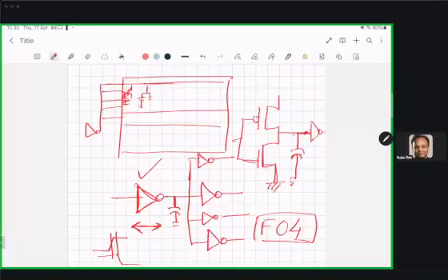On the other hand, we said that we need large enough memory, otherwise how will we do these big matrix manipulations? For example, I want to do image processing. So I have 4K frames coming at a speed of, let's say, 30 or 60 frames per second. If I don't have memory, how will I store them? My processor can't do anything without storing. So I have to store the data in data memory, and then I have to fetch it, work on it, and so on. So these are two contradictory requirements.